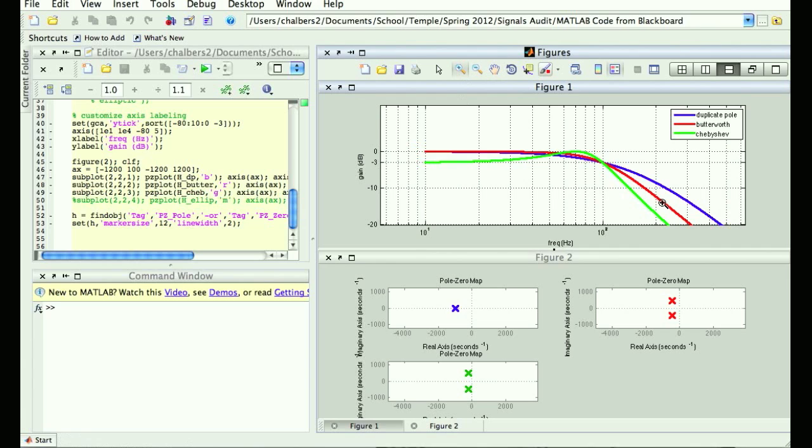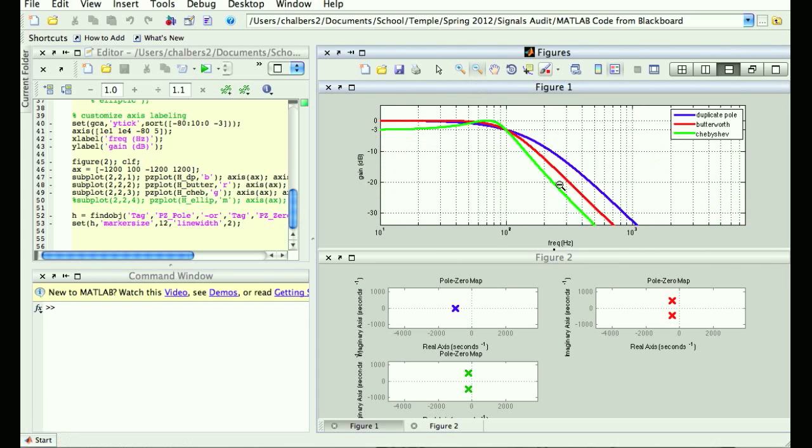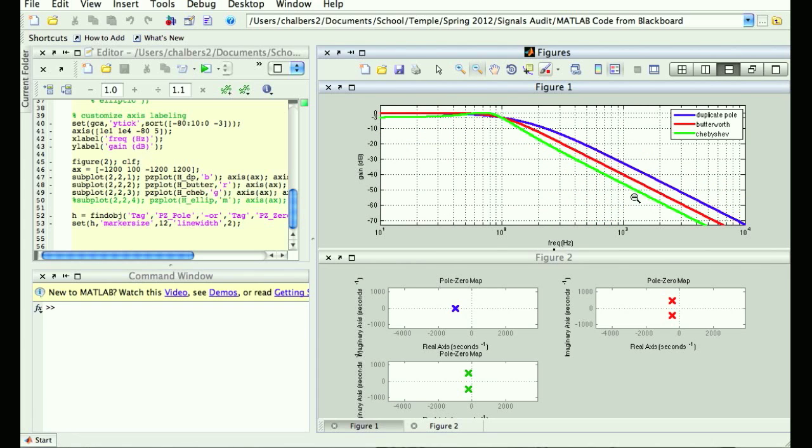So let's say the red signal is nice and smooth. You're passing every frequency with really high fidelity in the pass band. The green one is a little different. Some frequencies will be 3 dB down, and other frequencies will be 0 dB. They'll all get passed, but just a little bit differently. So if your application can tolerate a little bit of wiggle in the pass band, treating some of those frequencies a little bit differently, then the math says that in exchange, you can have better rejection in the stop band for free. Kind of zany, right?